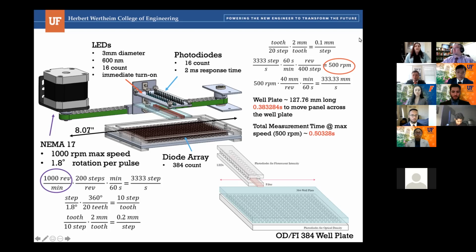To compensate for this, a controller that can implement a half step is used. A half step will move the system 1/10 of a millimeter per pulse, which is sufficiently precise for what we're using it for. Using a half step, the system can run at 500 RPM.